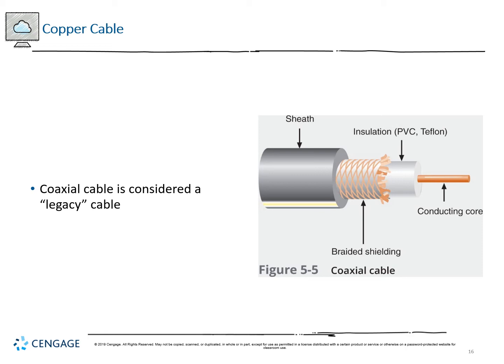What we see here is a multi-layer construction. We have a PVC sheath on the outside. It's the black, shiny plastic that's on the outside. The braided shielding that we see there is usually probably brass. Can sometimes be copper as well. Usually it's unlikely they're going to use copper for the exterior because it is a very valuable metal. It's better to use it for the conductor than just the braid.